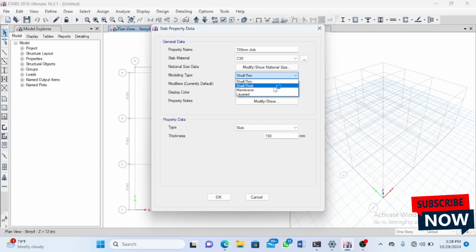So for the shell thick, it incorporates transverse shear deformation, making it ideal for thicker slabs, mostly when you're working with thicker slabs, and it accounts for both bending and in-plane action. And also the membrane actually ignores bending stiffness entirely, and it assumes that the slab carries load only through in-plane force. That's the tensile and the compressive forces. So we mostly use the membrane when we are designing shear walls or maybe diaphragms connecting to vertical structures. So that's it for the membrane.